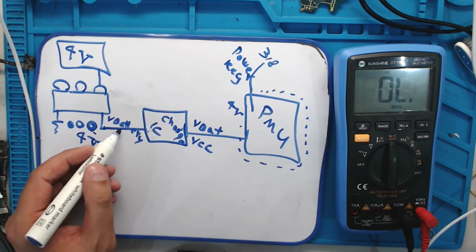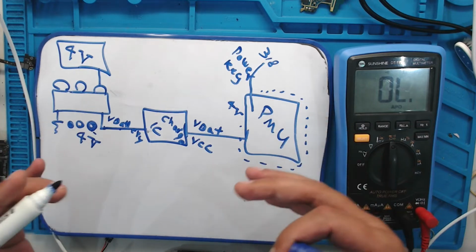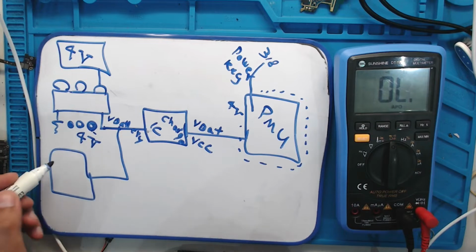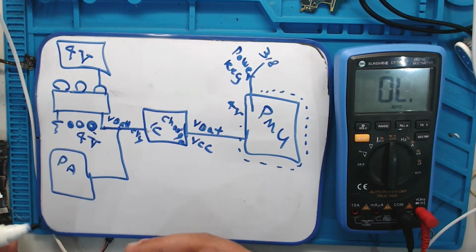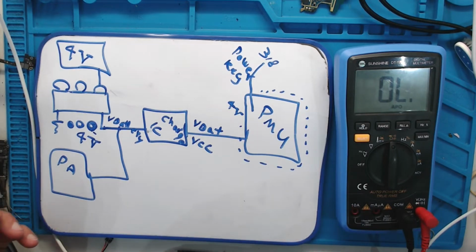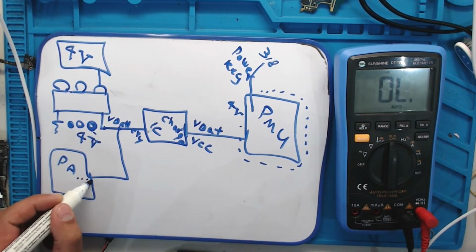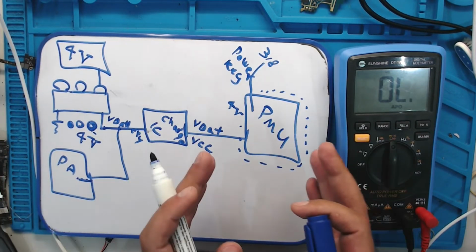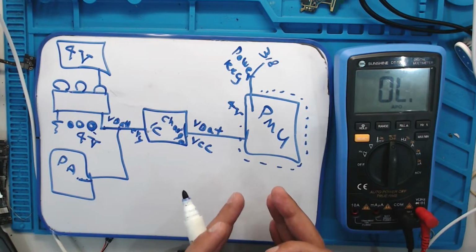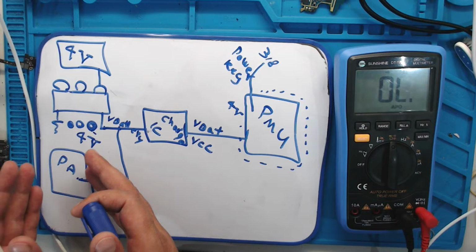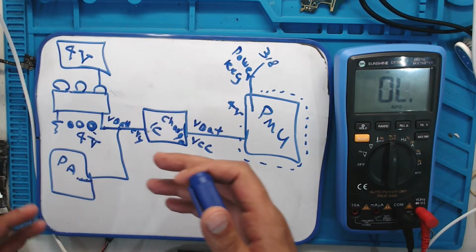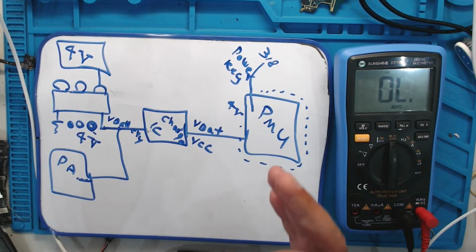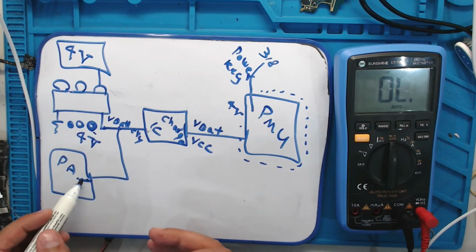Some parts on the phone need a 4 volts voltage for running. This voltage, for example, comes to the PA, or power amplifier, for the network. That needs 4 volts. The voltage comes inside the IC, but in standby the phone is not turned on. When you press the power button, the CPU or chipset starts processing and turning on the phone. After processing, this part is turning on. But before pressing the power button, there is just voltage there.